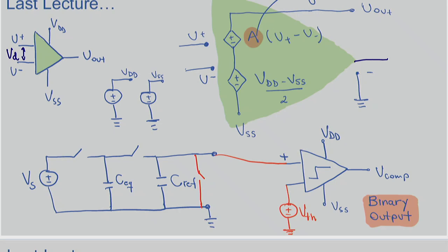And we connected the U plus terminal of a comparator to the capacitive touch screen, and we connected the U minus terminal of the comparator to a voltage that we called voltage threshold, which would be a voltage that would define when we had touch, when we had no touch, and take into account the errors that we had in the measurement. Okay, that's what we did last class.